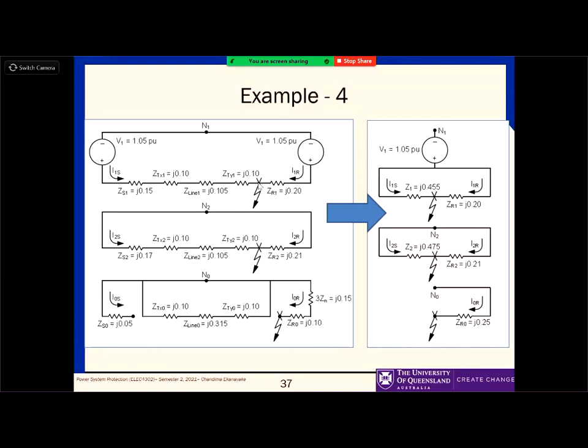So if you are looking at here, one generator is this side, the other one is this side. So you can use Thevenin equivalent circuit to find out what is the equal voltage, which will be 1.05, always, because the supply voltage at this point, if you open it, will be this voltage. And then this set of impedances and this impedance are in parallel. You can see that here. That is the simplification of this positive sequence network.